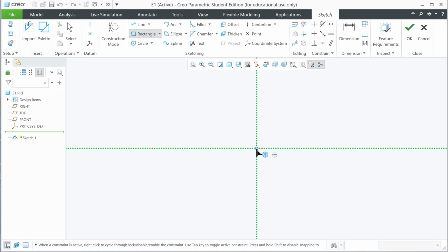That's an automatic relationship. And relationships are one of two constraint types that are used inside sketching. The first is dimensions. Like if you draw a line, you want it to be 5 inches, you can type in 5 inches. In this case, you could lock it down on that origin. That's your 0 marker in space, 0 for X, Y, and Z. And when we lock it down, it's a nice anchor point, and that cannot be moved. You could put additional WCSs and things, but that's what we're interested in.